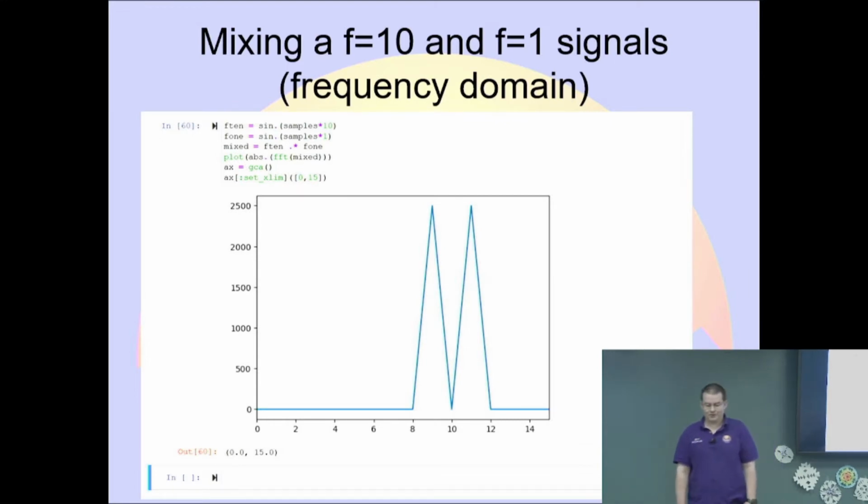So if we want to shift our data around on the carrier, we use a mixer, right? And you do that if you had a traditional hardware radio. But we can do it in software as well. So if I make two sine waves in the same way we just did, and I multiply them together, I get, in the frequency domain, two points. And they're bigger triangles because the scale on the x is different. So again, it's really two points. Just take my word for it.